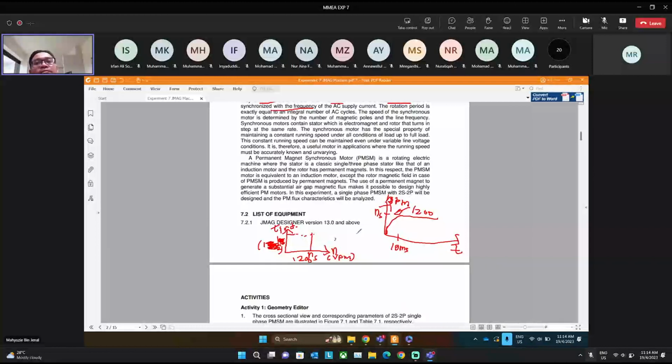So we have the pull out torque here. If you refer to the torque speed characteristic, we have the TPU or TPO. This is the pull out torque, with the rated torque over here. You can see that we are not able to control the speed of this machine; it is not a multi-level speed type of machine. Usually the torque speed would peak and then drop, as for an induction motor.